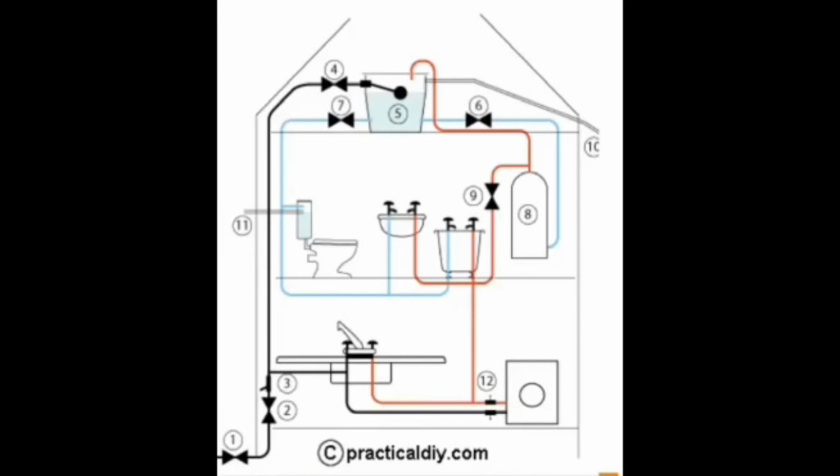The last one is the indirect pressure distribution or the indirect water supply. An indirect water supply system is the most common type found in modern houses. So the mains water comes in via a rising main and directly feeds at least one cold tap and the kitchen sink with potable water, and may also feed a washing machine, a shower, and an outside tap, etc.